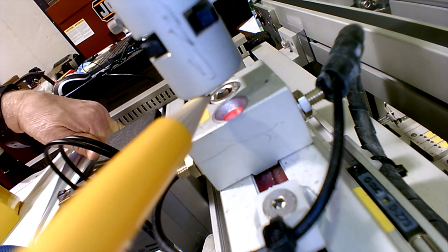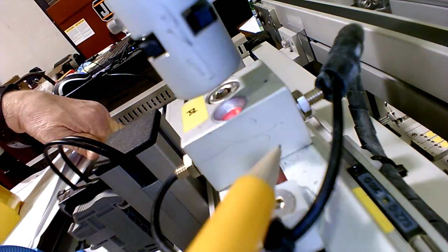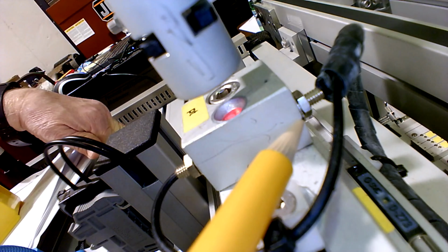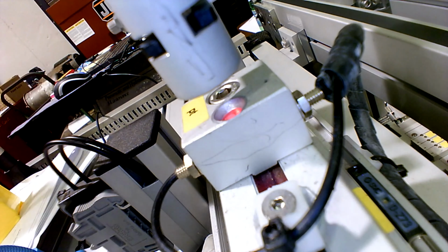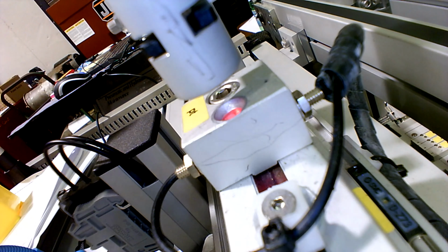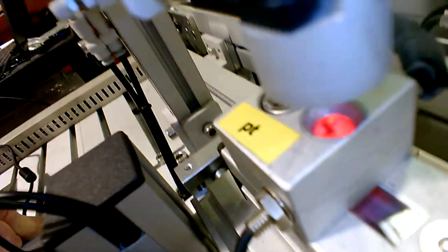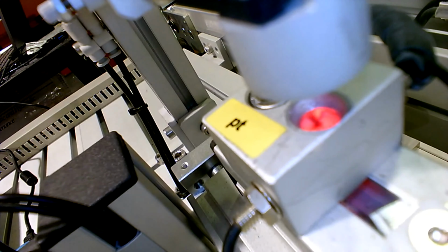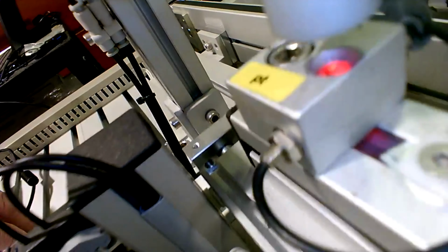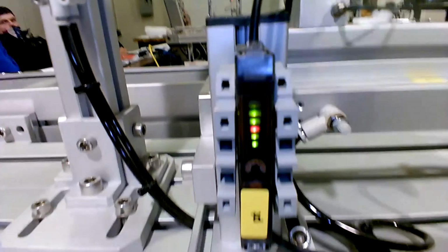And so look, if it drops a screw down in there, it blocks the beam. When it drops a screw, the beam will be blocked, and then the module where the fiber optic lines go knows when there's a screw there. So if you look down in the hole here, you see the glowing light down in there, right? That's the actual light that shoots through the hole. Now, right now, that light has actually got through there, and this fiber optic line picked it up, and it brought it back to here. You see the LED's lit?